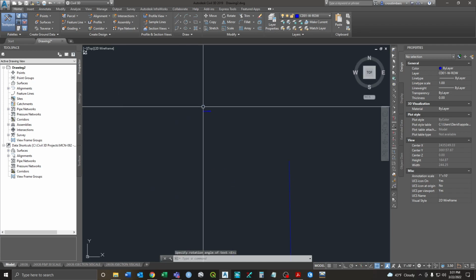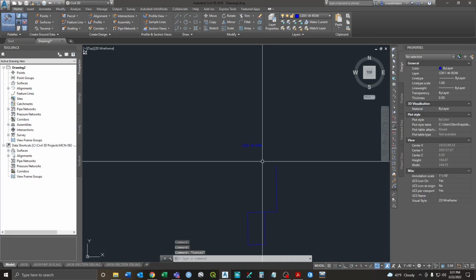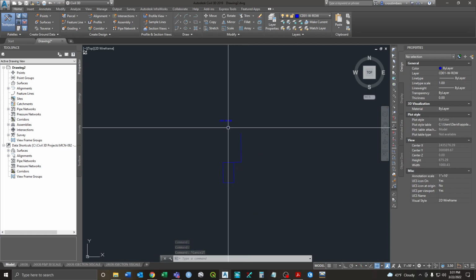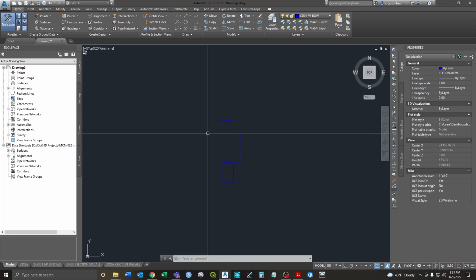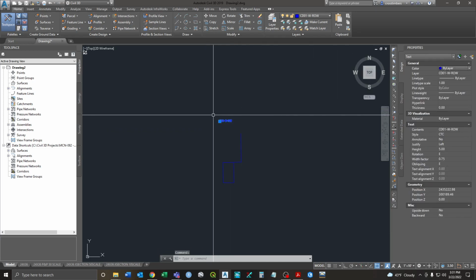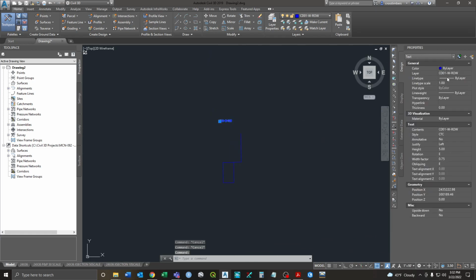Okay, and obviously that made that really small, so let's just, okay. And so, I don't know, can you see the blue very well on the background? I think can you do the letters in like yellow? Yeah. Even though it's on this layer, you just click it and come to the properties and go to color. So we set the layer to be blue, so it says by layer blue, but you can drop it and change to whatever. Okay. Yeah, that's easier to read, and I can make this a little bit bigger too.